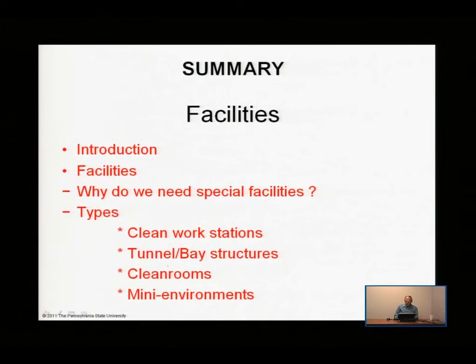And how do we do that? So we came up with the idea of these tunnels or bays, which are cleaned again with HEPA filters and have a very well-defined, clean environment in which we can move the samples back and forth. Of course, we had to worry about keeping the humans properly attired in those volumes, but we discussed that and the whole idea of clean room garb, which we introduced as early as Lecture 1.